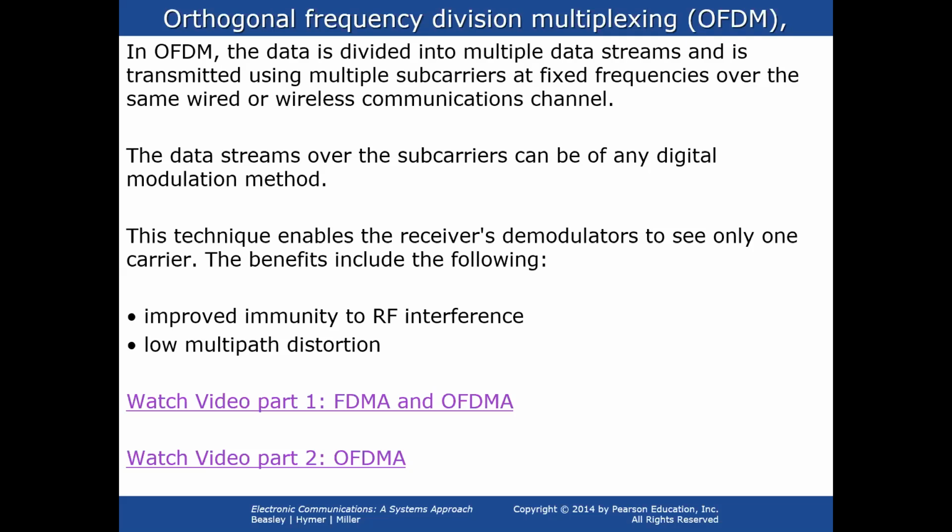Now this time sampled signal is converted into an analog wave by a digital to analog converter. Further, the composite waveform is modulated at the desired radio frequency for transmission. For example, an operator having a license for 2,320 MHz to 2,340 MHz. The 18 MHz will then be mapped from 2,321 MHz to 2,339 MHz using analog modulation. And finally, the eNode B transmits the signal over air.